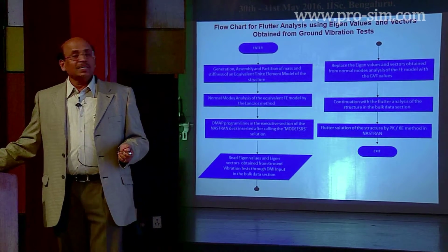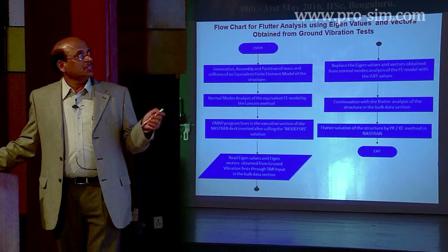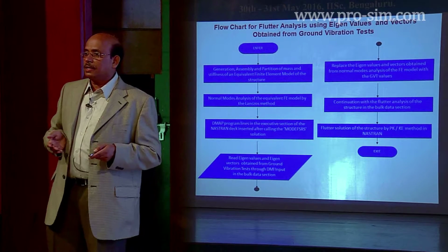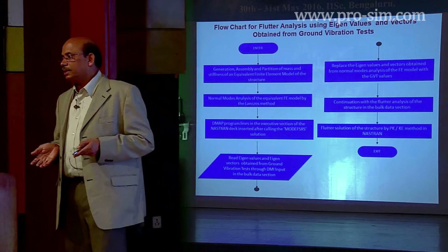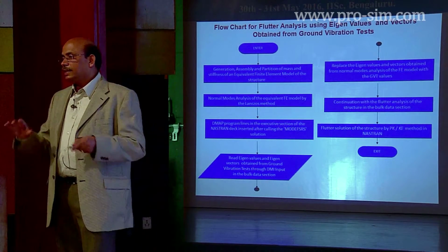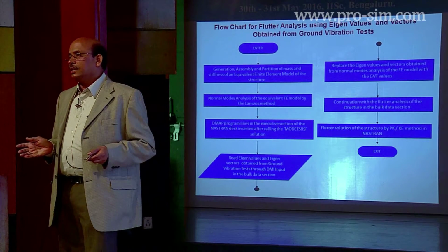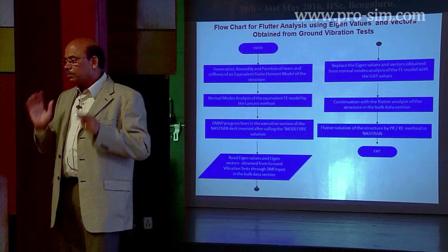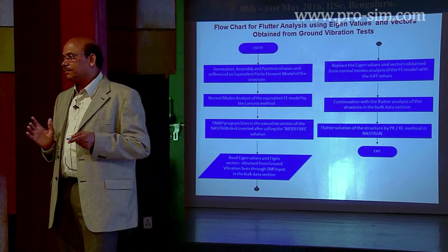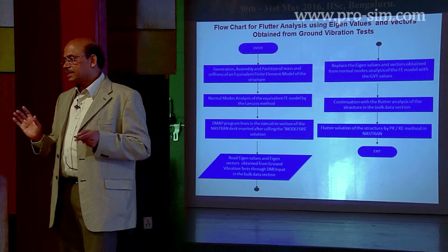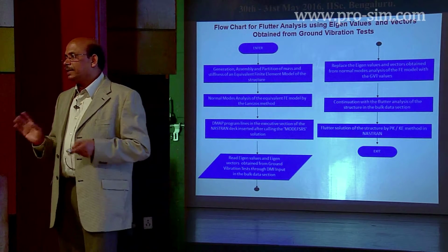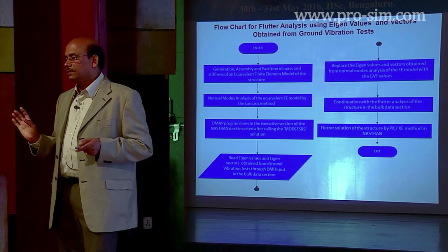Here is the basic algorithm that is shown. What we do is we conduct laser scanning of the structure that is to be studied. We create the complete geometric model of that. Then we actually go to the equipment or go to the aircraft. We do what are known as the vibration studies on that. We instrument the aircraft. We do the vibration studies. We capture the complete eigenvalues and eigenvectors, the mode shapes and frequencies, everything.